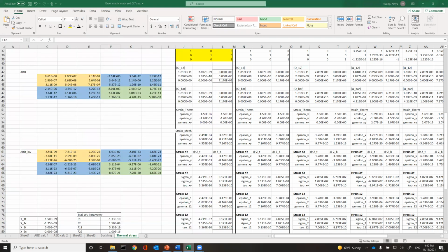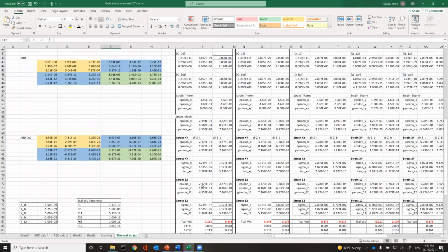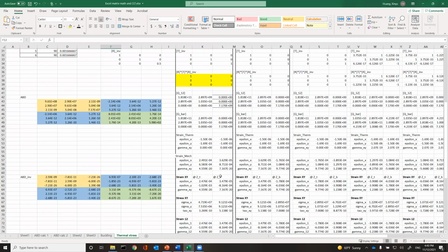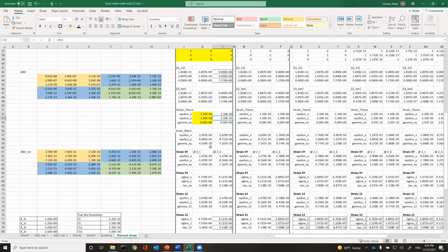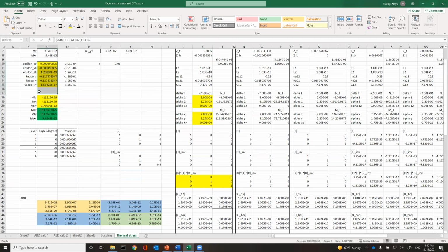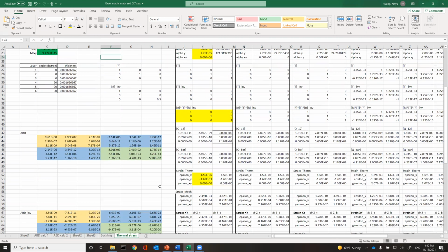So that's accomplished in my code like this. I figure out the free thermal expansion strain for each lamina, which is this matrix. This is at the top, the other is the bottom. They're the same, right? Then I subtract. This is the difference between thermal and total. This is my mechanical strain. I call it strains underscore mechanical. That's my mechanical strain. It's a subtraction of the thermal effect out of the total strain. The total strain is calculated using this set of numbers and a Kirchhoff assumption.